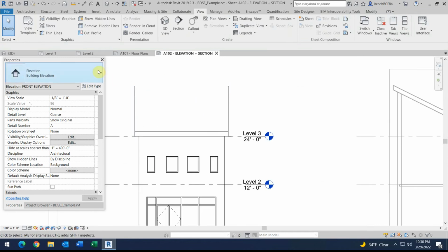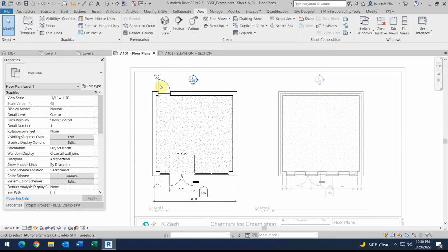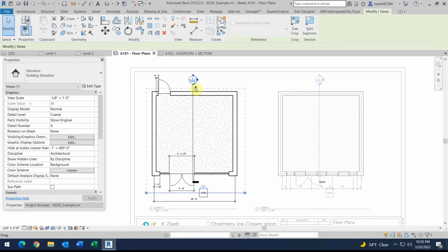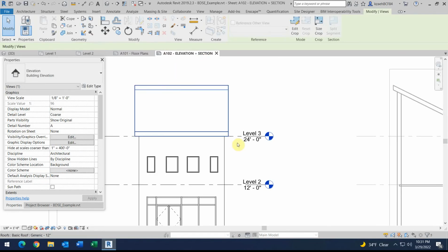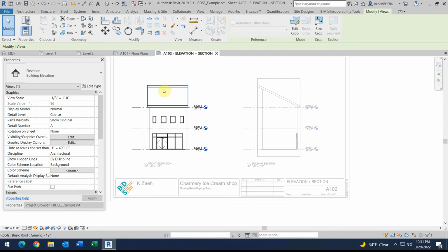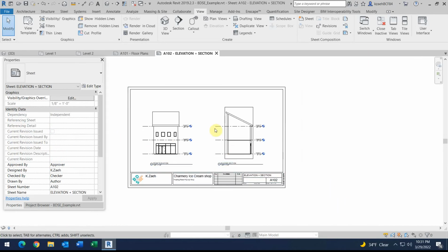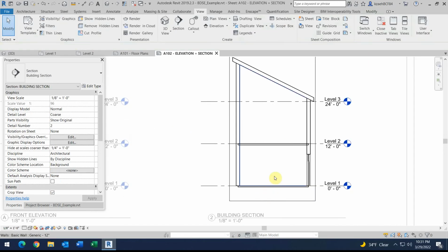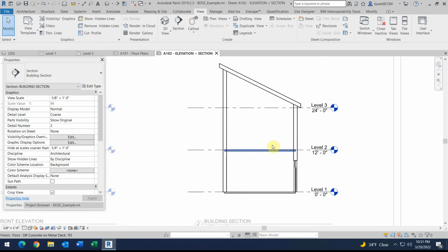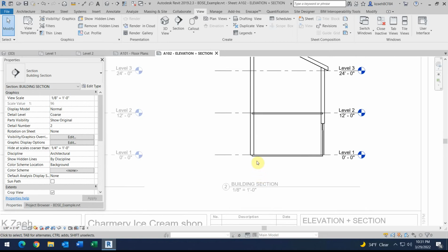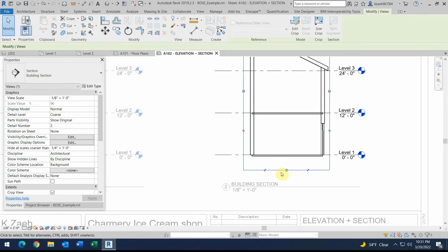Now you'll notice that line's still not showing up, even though I know that I fixed this to show the whole roof. There we go. I guess it was just glitching. Okay. So I now am going to double click outside and that will work. This one I need to turn off my crop region. So I'm going to double click here and turn off my crop region. So you'll notice right now that I think in this model I never made anything below here. Let's make sure. Yeah, I guess I never made my floaties.